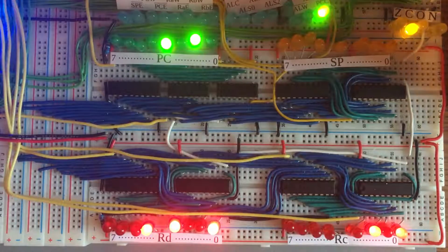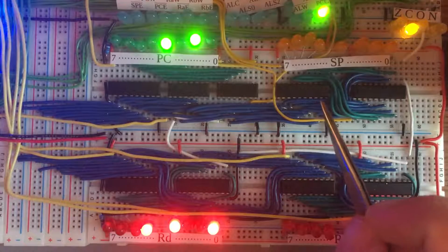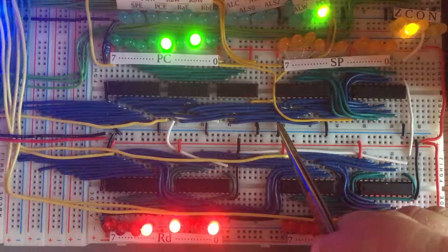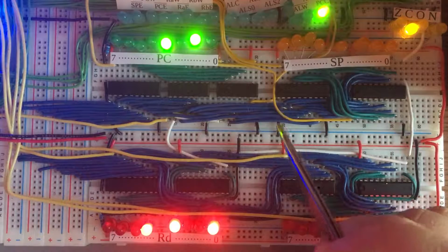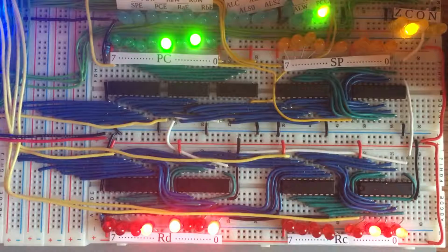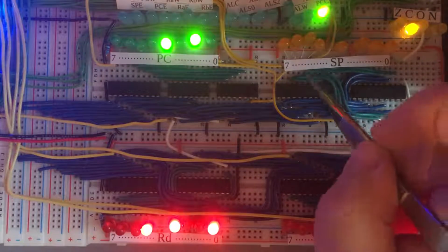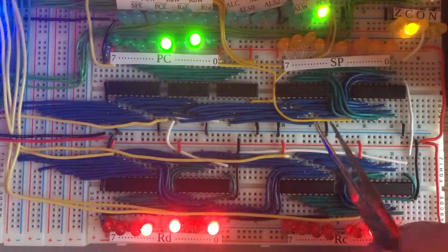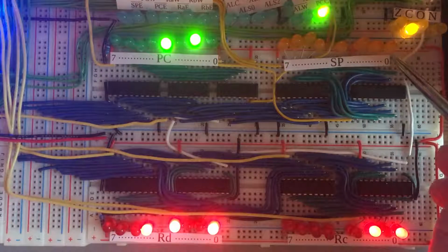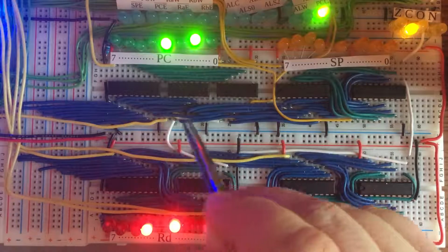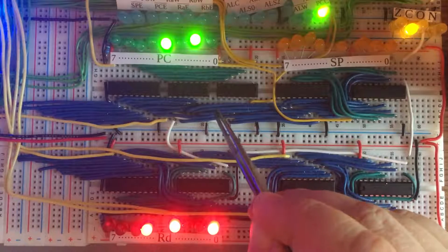And so all that we need to do there is, in the stack pointer, that direction signal is connected to a different value. So here on the stack register, it's actually connected to 0 volts, to ground. And on the C register, it's connected to 5 volts, as it is on the D register. And so in this case, it's high, which means that the signal is going that way. And in this case, it's low, which means that the signal is going that way. And the only reason for that is geometry, because I wanted to put the LEDs on the stack pointer on the top here. And because actually, when building the program counter, it turns out that it's more practical to have the bus on the bottom side.